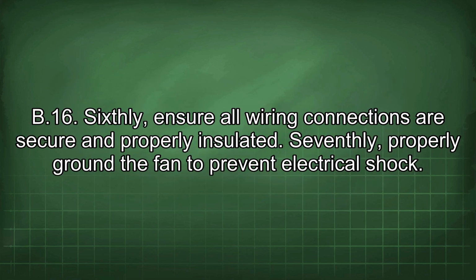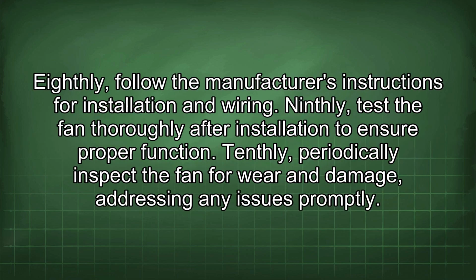Sixthly, ensure all wiring connections are secure and properly insulated. Seventhly, properly ground the fan to prevent electrical shock. Eighthly, follow the manufacturer's instructions for installation and wiring. Ninthly, test the fan thoroughly after installation to ensure proper function. Tenthly, periodically inspect the fan for wear and damage, addressing any issues promptly.